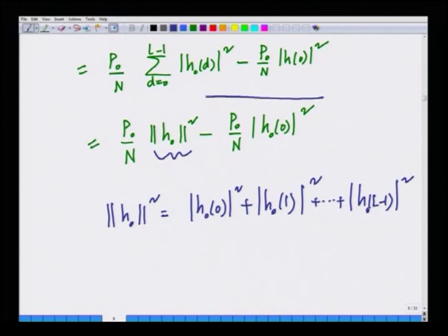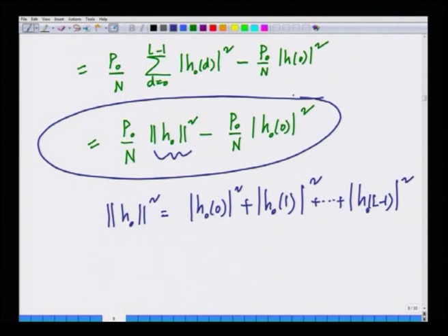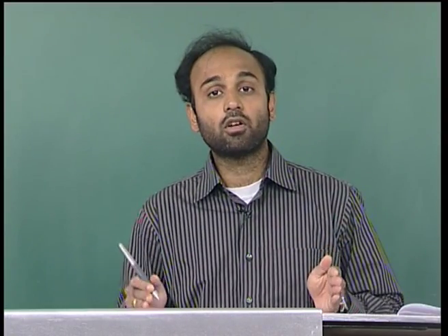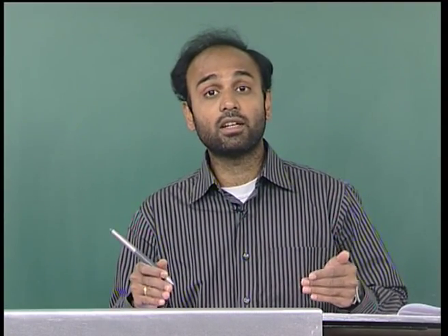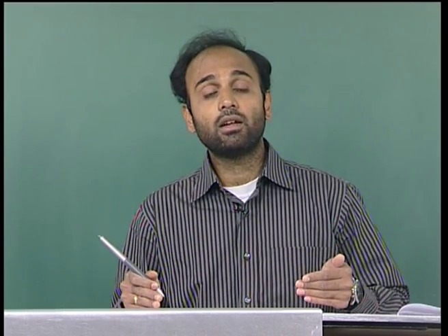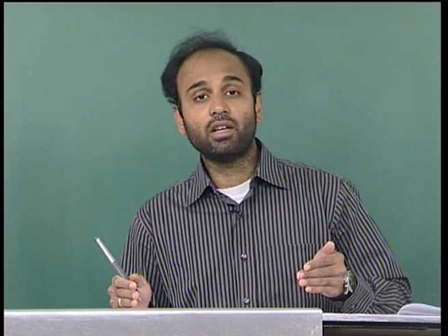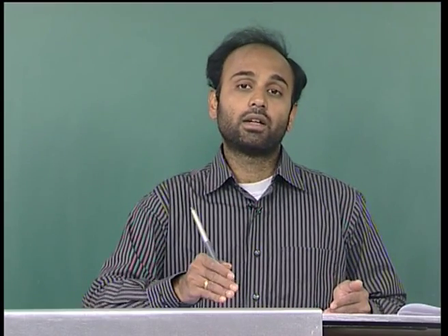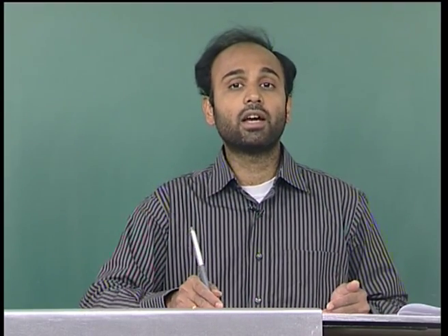All right. So, this is the interference power corresponding to the multipath interference, which consists of the L minus 1 components of the same user. So, this is the interference similar to the rake receiver, which interferes with the desired component of the desired user.